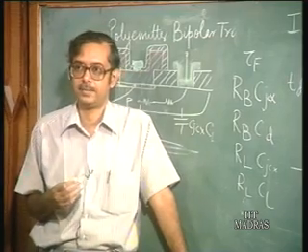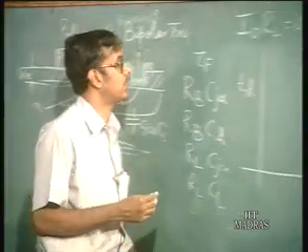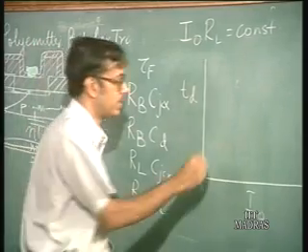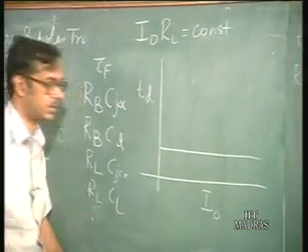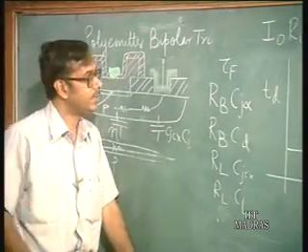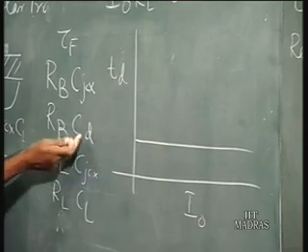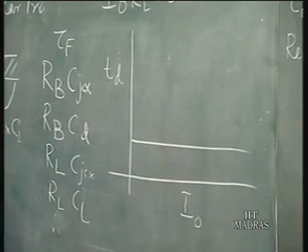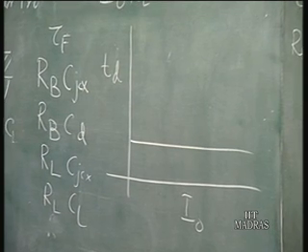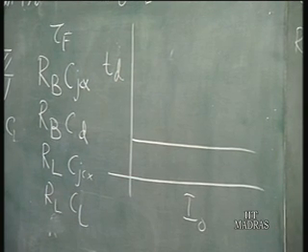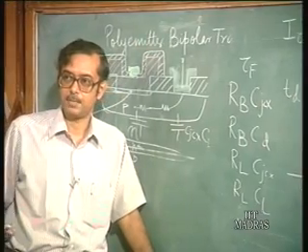in the ECL gate? So if you look at these components, you will find that tau f is independent of I naught, so it is going to be something like this, a constant. Then you have other components, say CD. Is CD dependent on I naught? It is dependent on I naught, so CD is proportional to I naught.